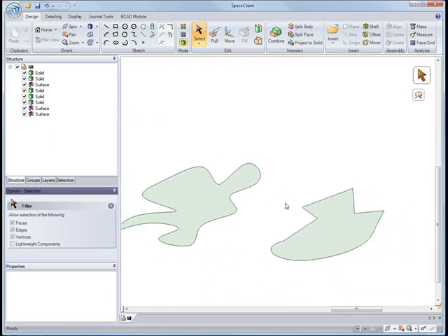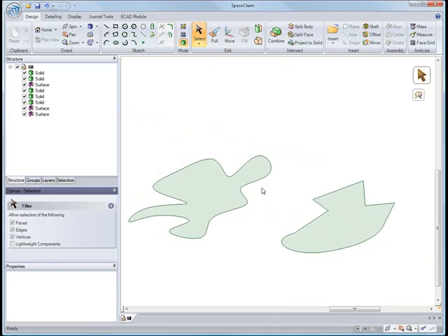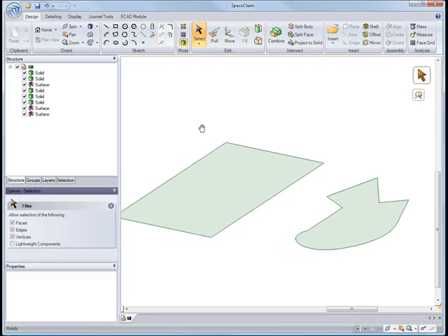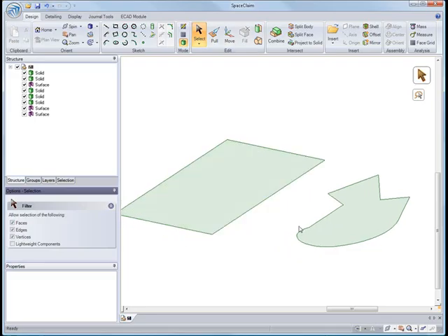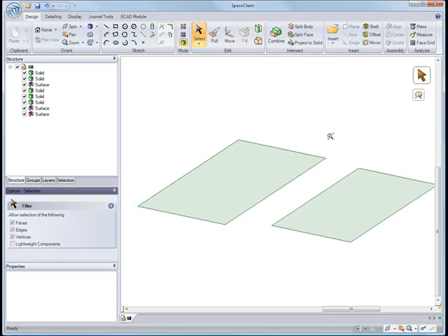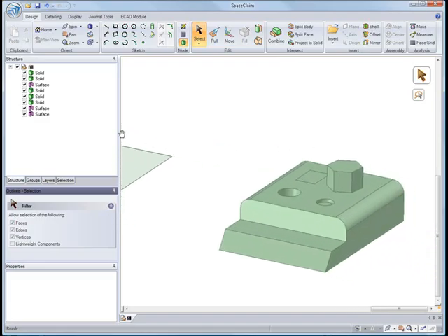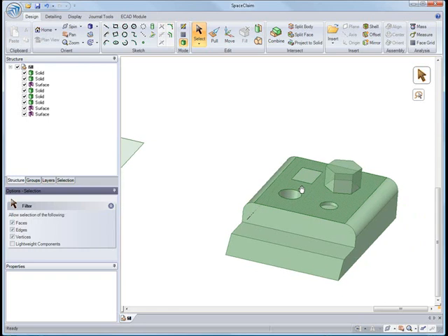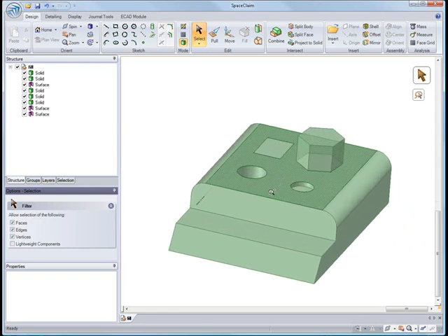Now with these two examples we see a spline region, and if I select on the edge and hit fill, it basically extends that spline out to get your maximum XY directions, and you have one rectangular surface. And the same can be said for the surface to the right of it, with a series of lines and arcs. So now let's move on to our solid, which is where I use fill the most.